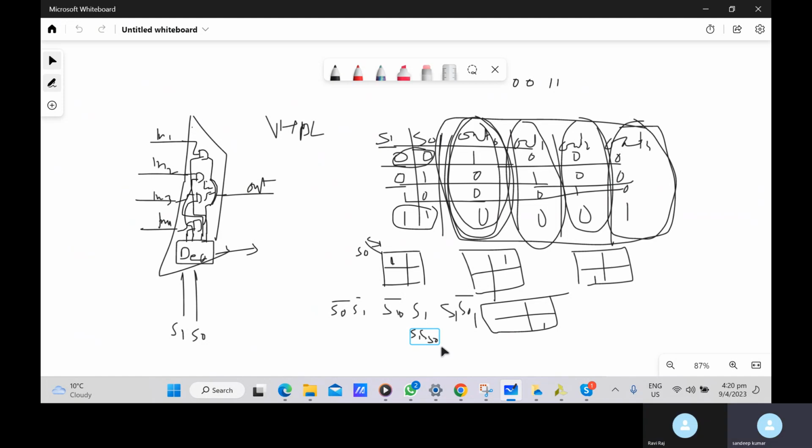In a real scenario, we will always write with 1 and 0. Whenever select has some valid value, only then will we treat the output as valid. Otherwise, we will not treat it as a valid output. So it does not matter if select is high impedance or X, we don't care what output comes; it can select 7 or anything. Basically, we are trying to avoid extra hardware. If let's say you have an extra selection when S0 is something else.